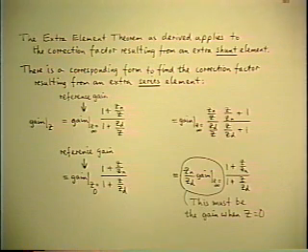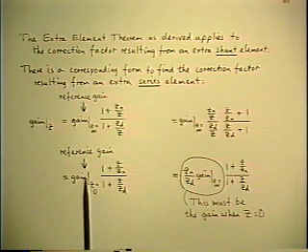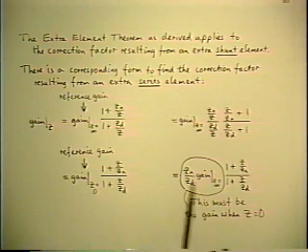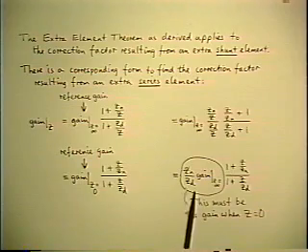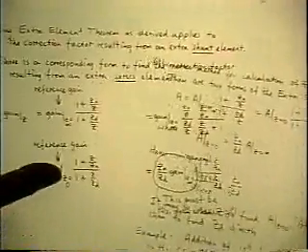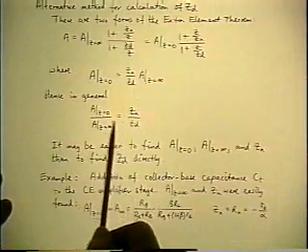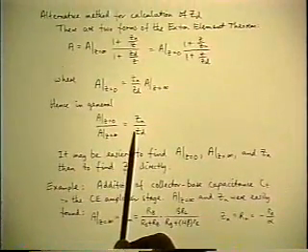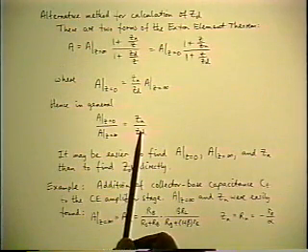Now, there was one aspect of that that we weren't concerned with at the time, but we can now use. Namely, the gain when the extra element is zero is the gain when the element is infinite multiplied by the ratio of the two driving point impedances, which is this, or rewritten in a symmetrical form, this part of it, which is also the dual of the frequency response interpretation.